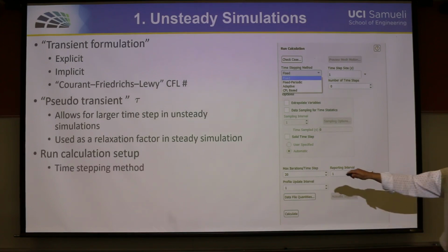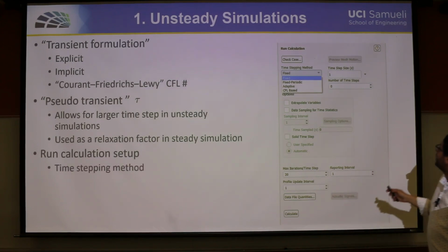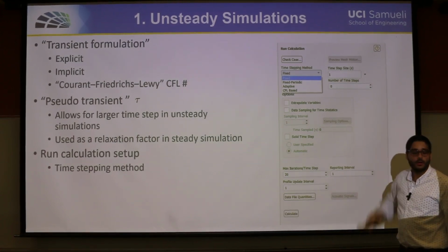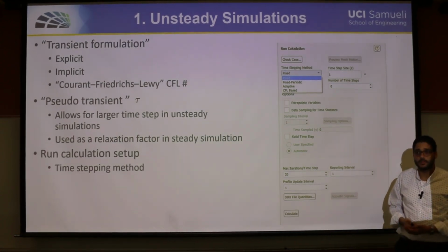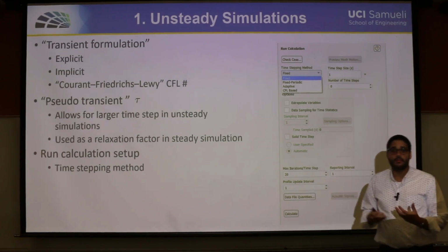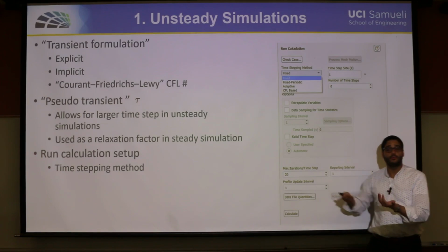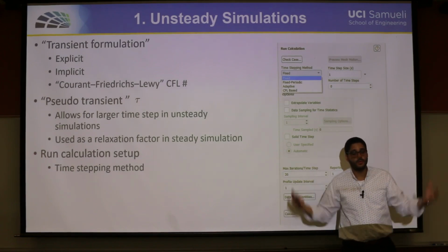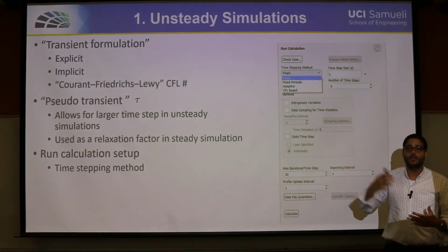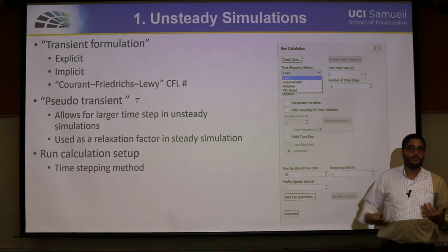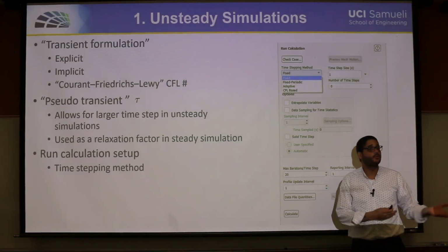I've been talking about the time stepping method, but before specifying the number of time steps, let's consider that we are gonna do a simulation with a fixed time step. So how do we select the value of the time step? For the grid or the mesh, we said we start with a very coarse one, and then we keep refining our mesh till we reach a grid independent solution.